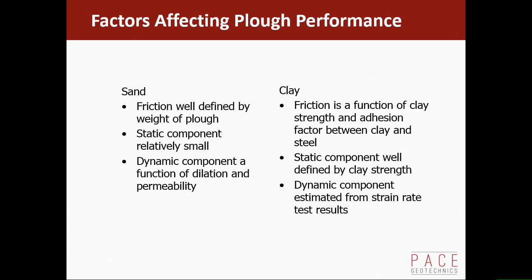In sands, that's actually relatively small. In clays, it's a simple passive resistance calculation and fairly well defined. In clays, the dynamic component we can estimate from testing clays at different shearing rates, and is fairly well defined, so that's not too much of a problem.